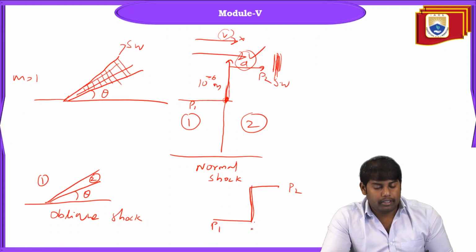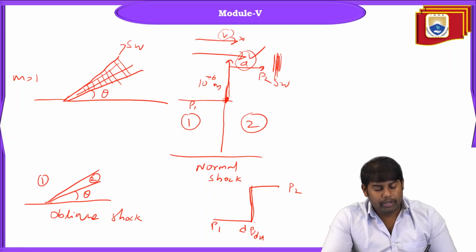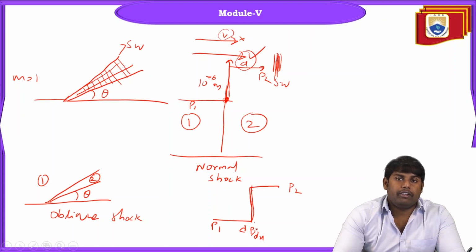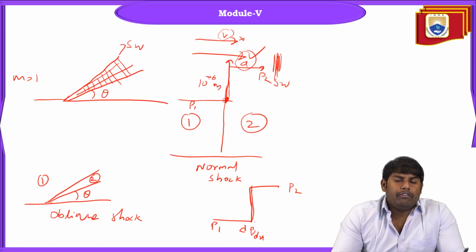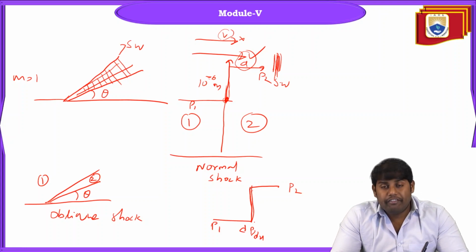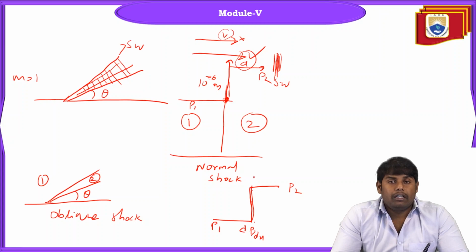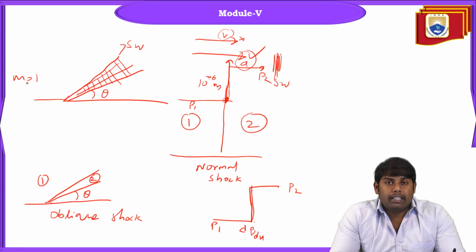At this point, what will be the value of the derivative? Let's say dp by dx. At this point, what happens? So we have 0 actually, p1, p2. Okay, sorry, this would be infinity. Why? Because the x point will be the same. Right. So therefore, the differential terms cannot be applied to capture the shock. Why? Because the derivative doesn't exist at the point of the shock. So that is the major concern with the differential methods.